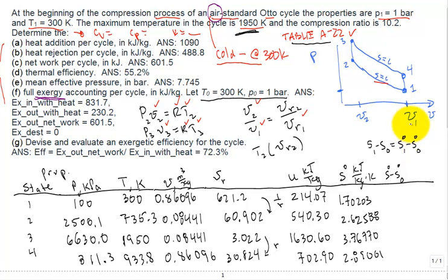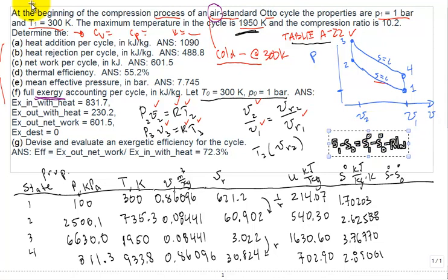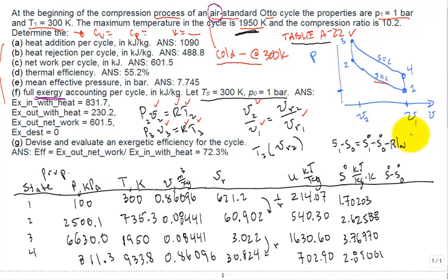These are that symbols, and then you would put the minus, the R, natural log, and I ran out of room. I'm going to move that over so I can see that equation. So it's equal to minus R times the natural log of P1 divided by P naught. Okay, so what I'm going to do is not just calculate the difference in the low pressure, like 1 atm, changes in entropy, but the full thing accounting for the change in pressure compared to the dead state pressure.